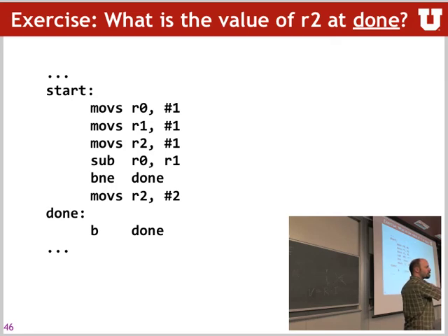Carry flag gets set? Why? That's what this says. On the move. Oh, that's on the move. Why would you set the carry flag? The carry flag happens when you have an overflow in an unsigned add, right? If it overflows, then the carry bit gets set. So Z equals 0 still.